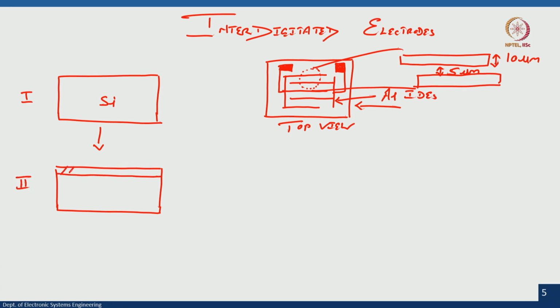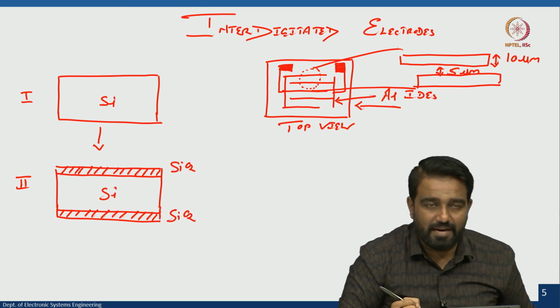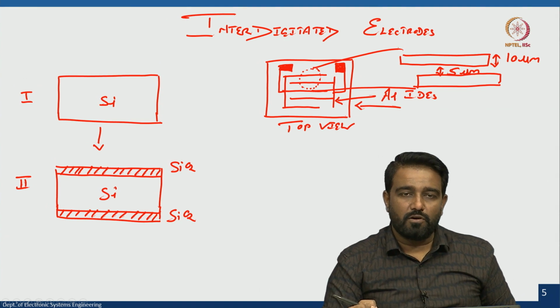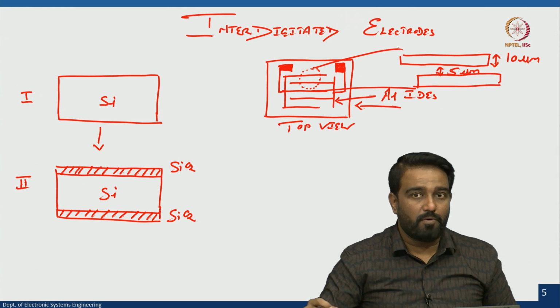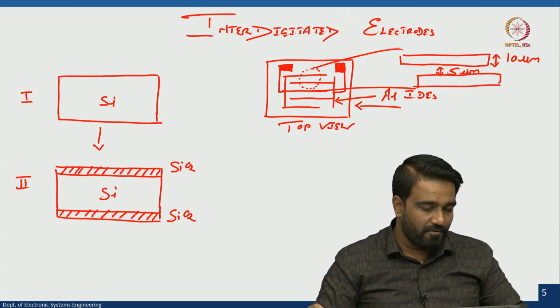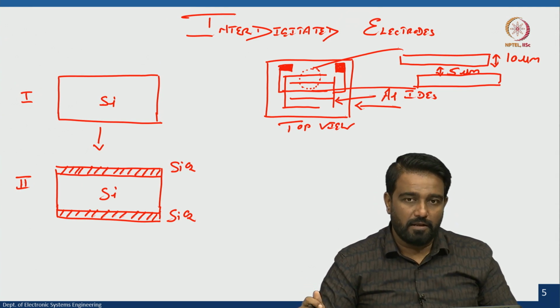Now, when you place the wafer into the furnace, the horizontal tube furnace, the oxide will grow on both sides. Why? Because oxygen will react with silicon on the front and back side of the silicon. So, you can grow silicon dioxide front and back. Now, we will take an example of wet thermal oxidation, so that we have about 1 micron thick silicon dioxide.